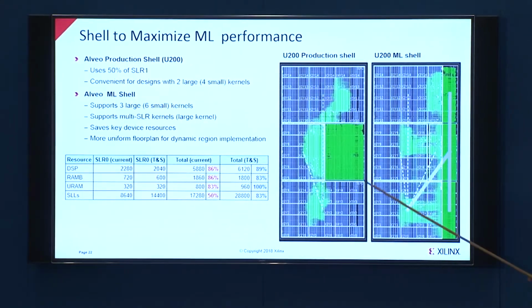Typically, when we are using FPGA as an accelerator, it takes some area away for doing all these support functions. When you write your application, it sits in this reconfigurable area. This is our standard shell. When we build the FPGA, this is a VU9P FPGA. There are 3 slices of it, and we have taken half of one slice. The logic it has is PCI logic, then 1 MIG logic as well as DMA logic.